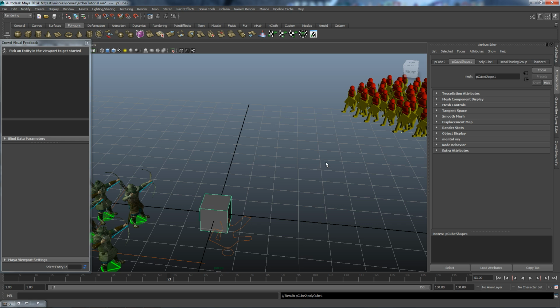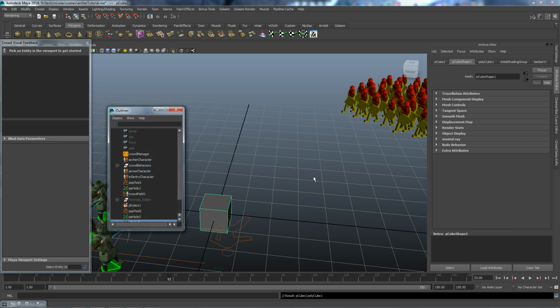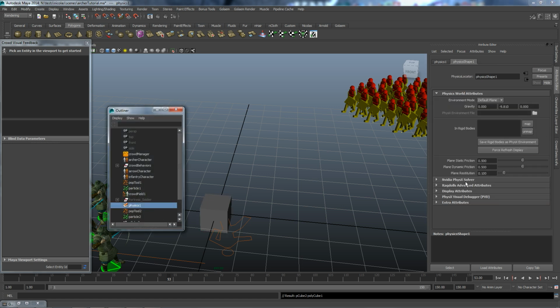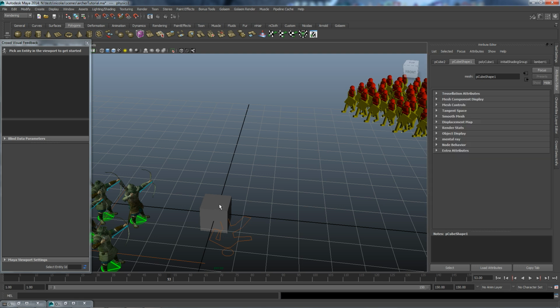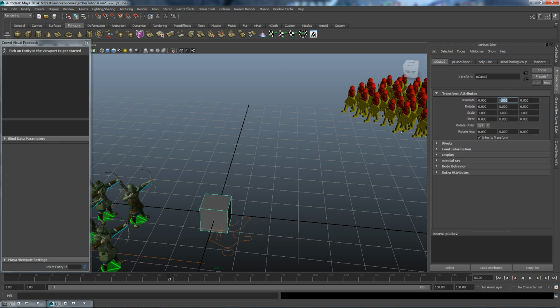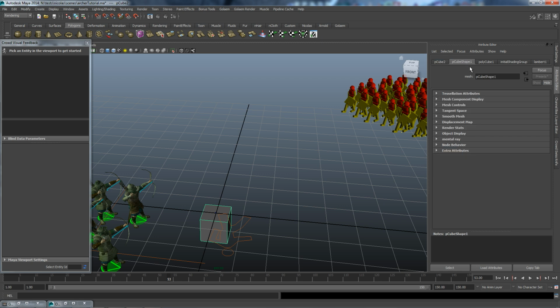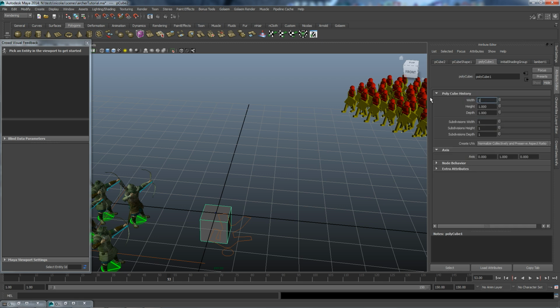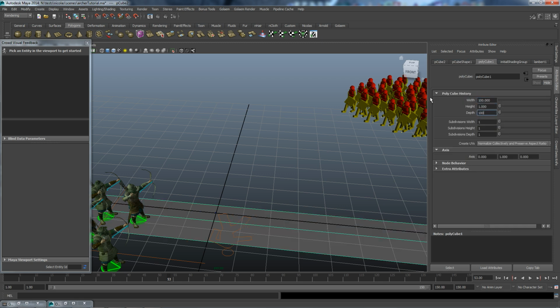If at some point you have defined a surface instead of a volume, one way to have accurate collision detection will be to increase the physics solver substeps, so add more substeps, so collision detection will be more accurate. So here I'm using a volume, so that's not going to be a problem, I guess. And I want to change its position a bit, so it's right at the same level as the grid. Change its size as well, so 100 should be fine.